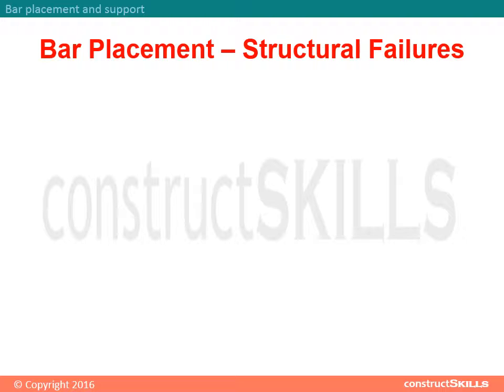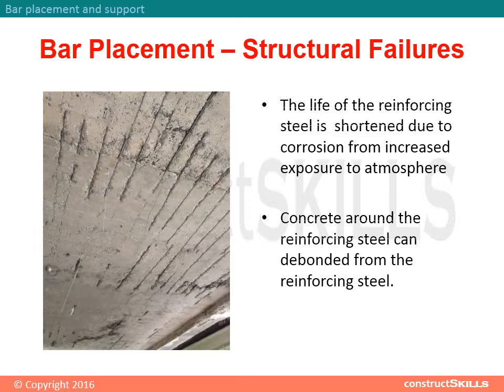Structural failures in bar placement. The life of the reinforcing steel is shortened due to corrosion from increased exposure to atmosphere. Concrete around the reinforcing steel can also be debonded from the reinforcing steel.